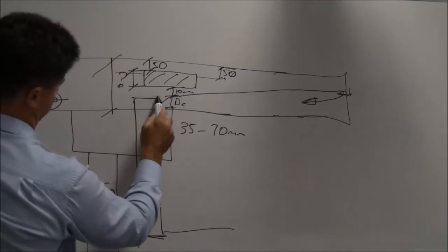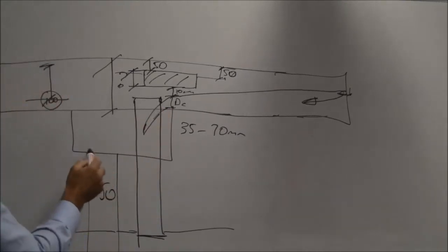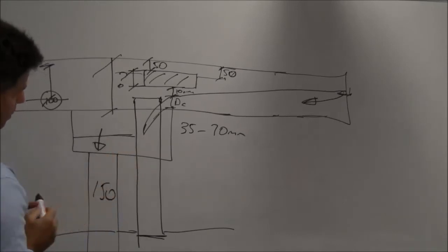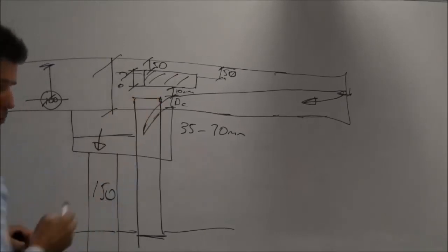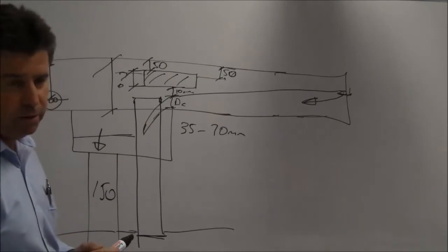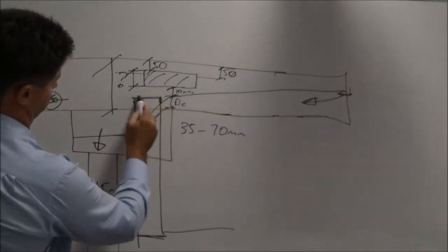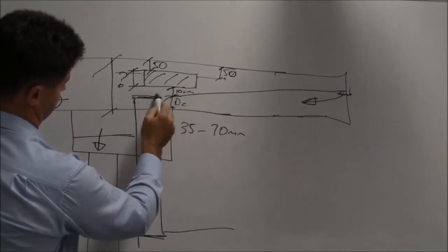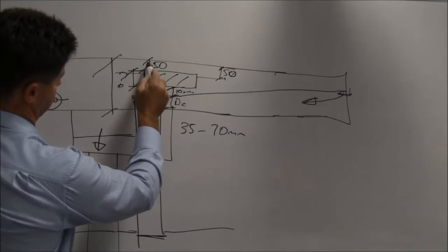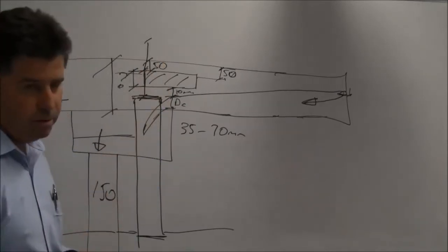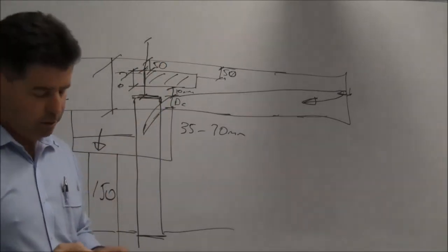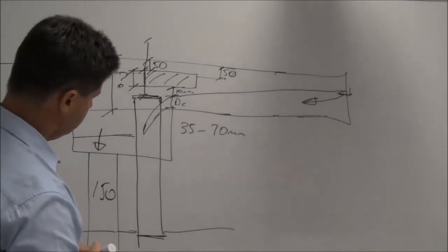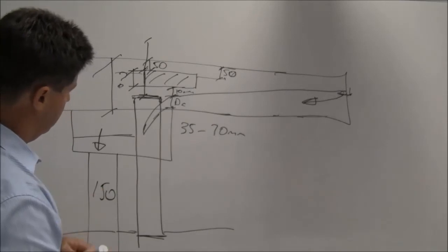Yeah, okay. So that's my overflow. In my normal calculation down here, if I needed 50 mil of water over the top of this outlet, then I still need 50 mil of water over the top of that overflow to make it work. So if I put that 150 overflow 45 mil above the bottom of the gutter, then my 50 on top, plus my 50 freeboard. So it was the critical depth plus 50 that you use as a rule of thumb.